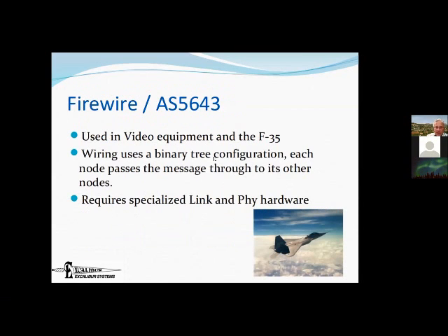Now, Firewire is another example of a bus used on the F-35, so it's a very, very up-to-date military bus. And it neither does point-to-point like 429, nor does a single wire for the bus like 1553, but it uses a binary tree configuration. Just by way of an example of different ways you can do things.